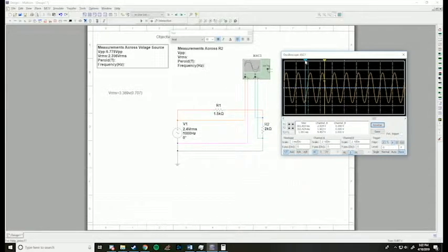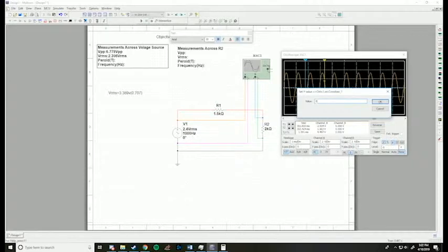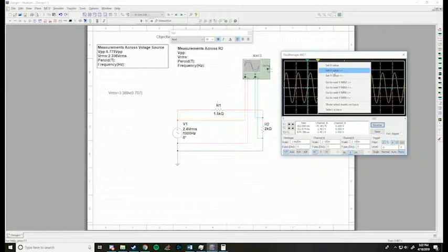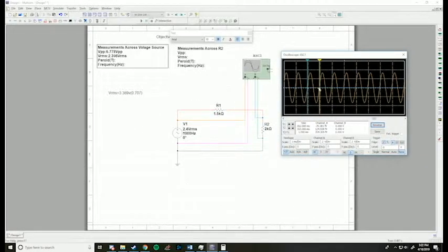So what we're going to do is set the y value this way of 0, and then get this one, go to the next y value of 0. And then the space in between here is going to be our period. That gives us a period of 1 millisecond, or 0.001 second.